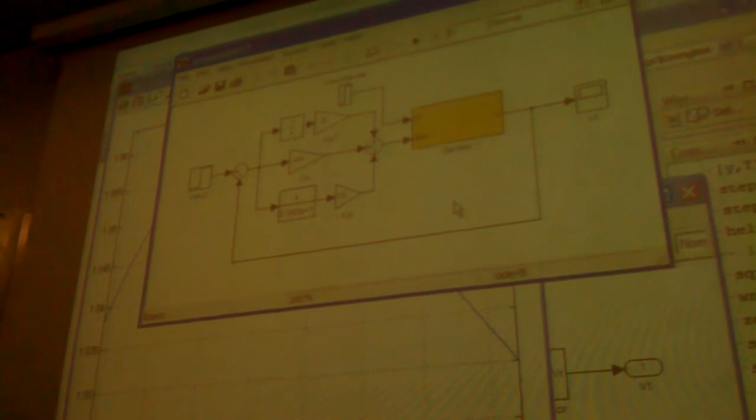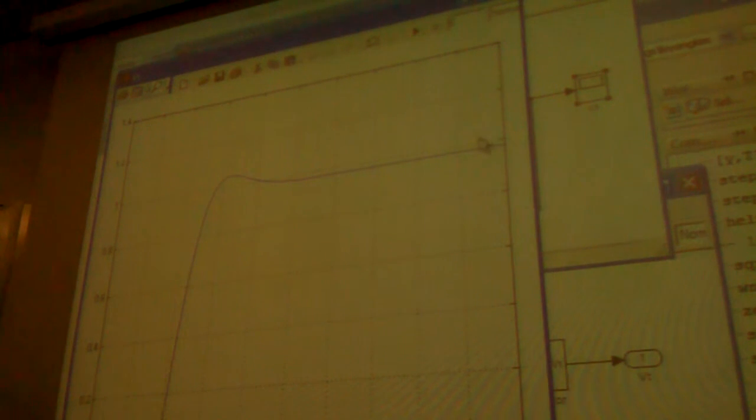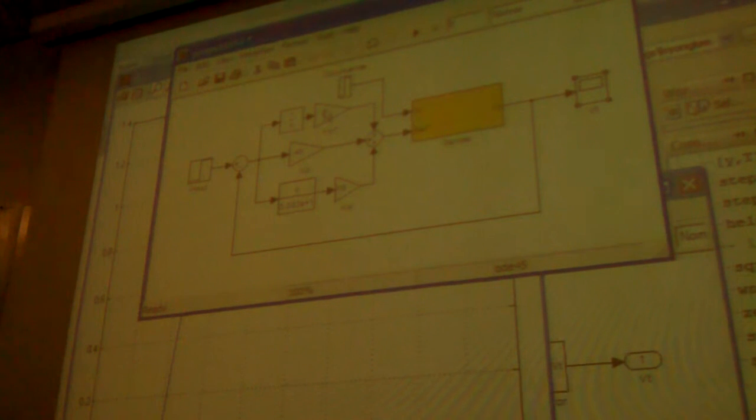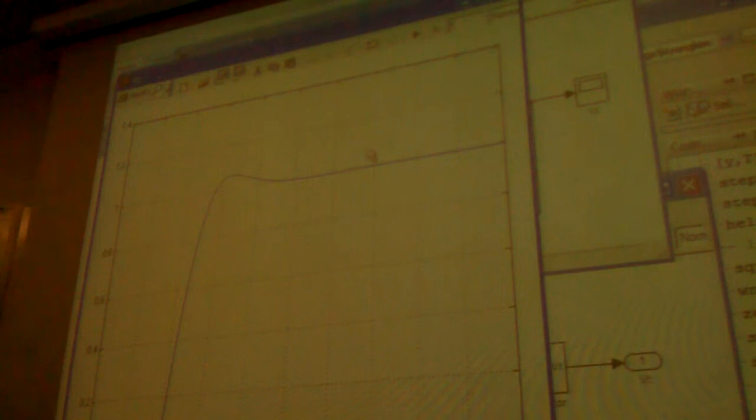Now if you run with 5 and 10 on this side, it stays at this level here. Now, with the integrator, I add this one at about 5. If you run it, your steady-state error is 0. It's not high yet, but it's less than 3%.